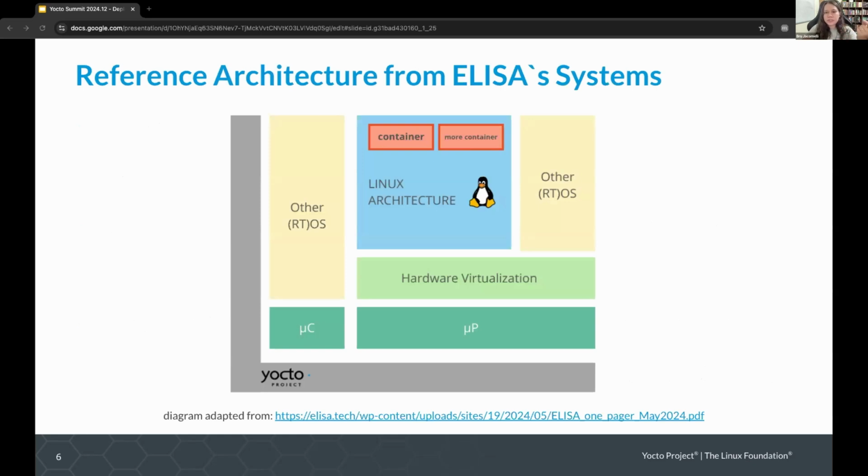We reference the Yocto Project as the foundation due to its reproducibility, which is crucial for safety certifications, strong community support, and its capacity to deal with the growing complexity of embedded systems. Then we can separate the applications at the processor level using virtualization systems within Linux and also using reference systems such as Automotive Grade Linux that we will use to demonstrate later. And if the systems require microcontroller solutions, like often happens nowadays, we can integrate an RTOS such as Zephyr.